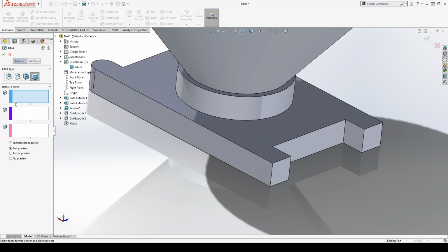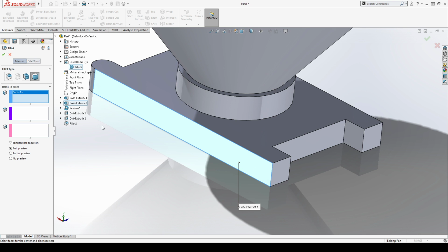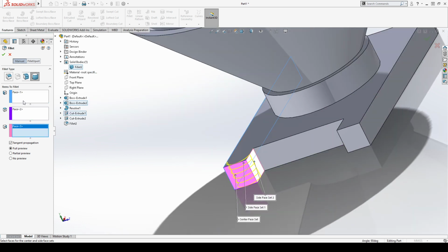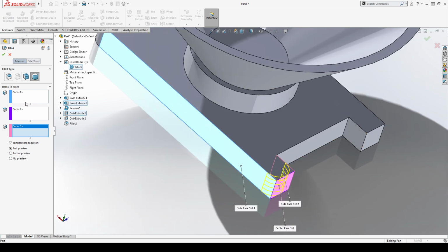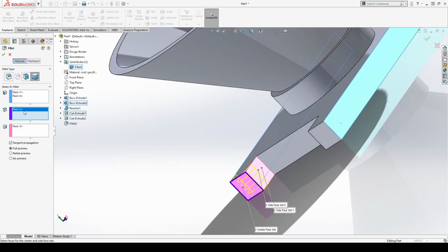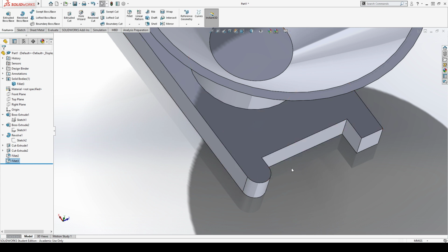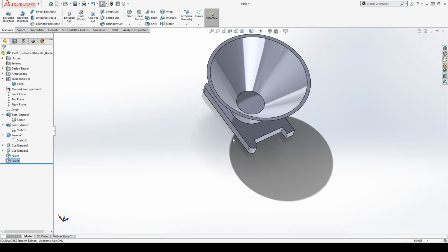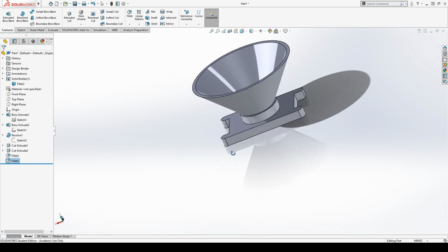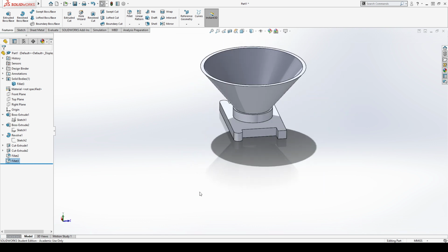Then, fillet, full round, 1, 2, 3. Let's see if we can do another one here. 1, 2, 3. Just letting us do. So yeah, when you're creating this kind of fillet, it does have to be continuous. You can't make two fillets at the same time, so it's not the best tool for doing the full round. In this case, maybe that sketch tool would actually be better at accomplishing the job here.